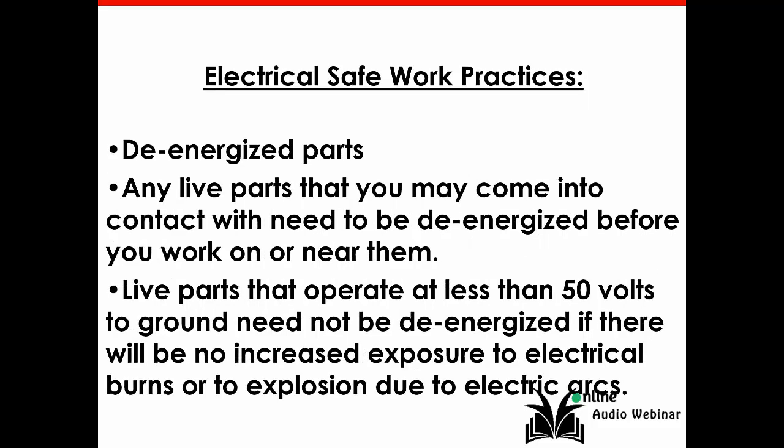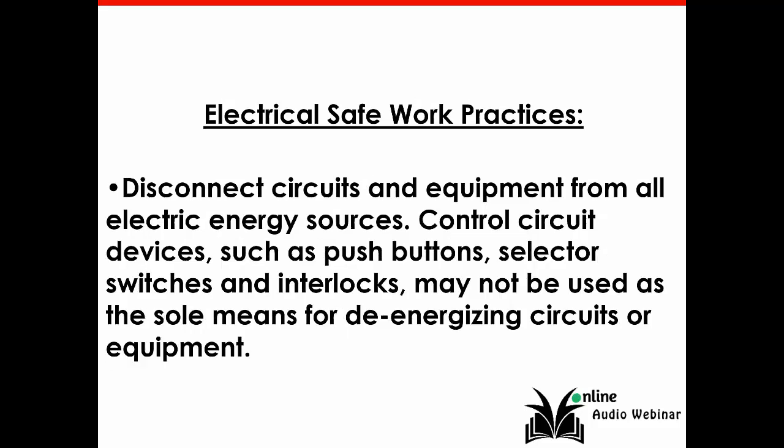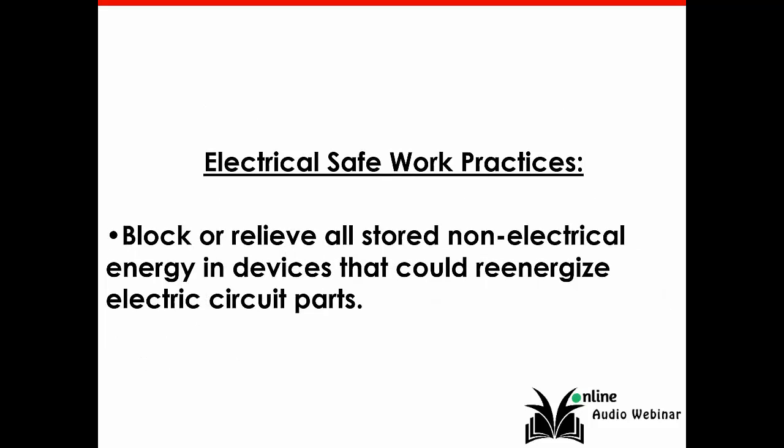Electrical safe work practices, this is where lockout tagout comes in, are de-energizing parts. So you want to lockout tagout of de-energized parts. So you want to disconnect circuits and equipment from all electric energy sources and release stored electric energy. Block or relieve all stored non-electric energy in devices that could re-energize electric circuit parts.